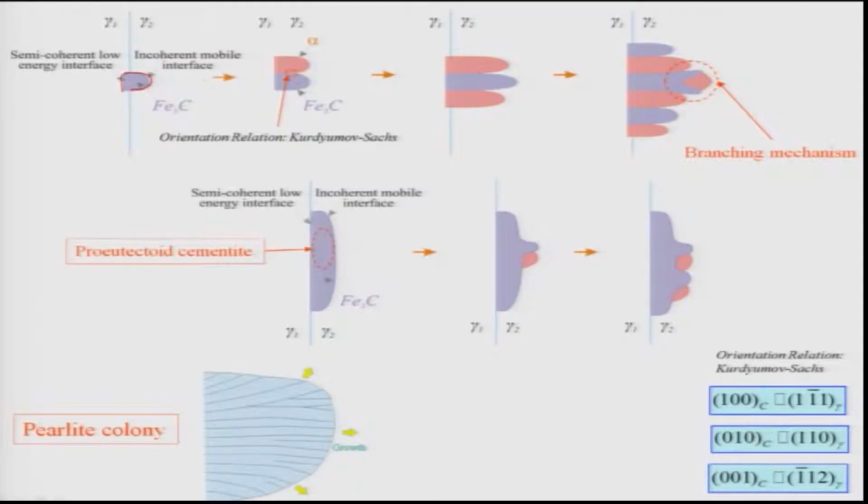So, as this Fe3C grows into the gamma 2 grain, it requires carbon. All the carbon from the nearby region will diffuse into it. That is how it can achieve a sufficient amount of carbon for its growth. And because of carbon diffusion from these nearby regions in the gamma 2 grain, the adjacent regions will become lean in carbon concentration, because carbon is diffusing through the gamma and reaching the Fe3C nucleus to grow.